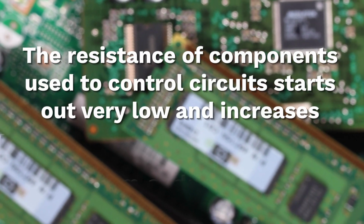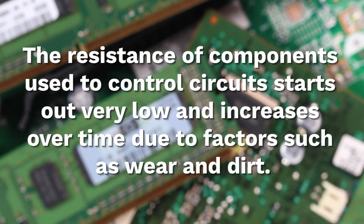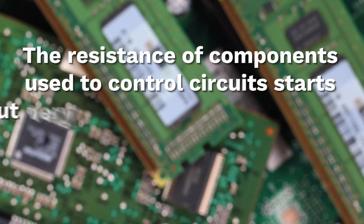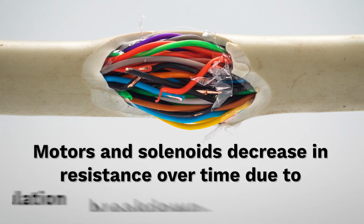In general, the resistance of components used to control circuits, such as switches and relay contacts, starts out very low and increases over time due to factors such as wear and dirt. Loads such as motors and solenoids decrease in resistance over time due to insulation breakdown and moisture.